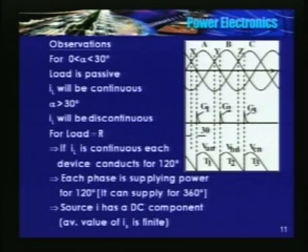Beyond 30 degrees, current will become discontinuous, because beyond 30 the instantaneous value of the outgoing phase goes negative, and you cannot have a situation wherein the voltage across the resistor becomes negative in an AC to DC power conversion. Now I am not going to draw the voltage across the blocking thyristor.